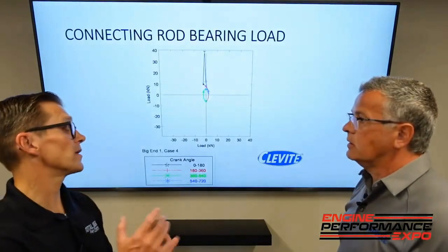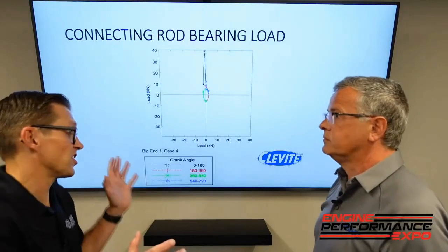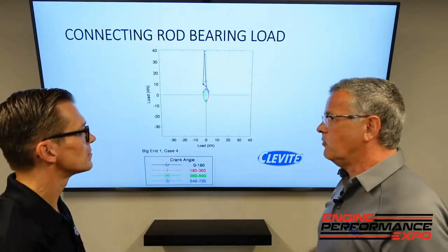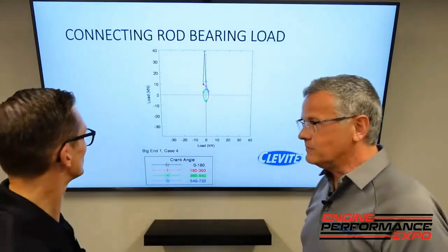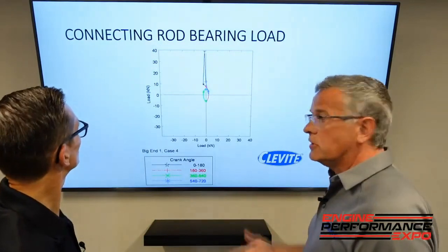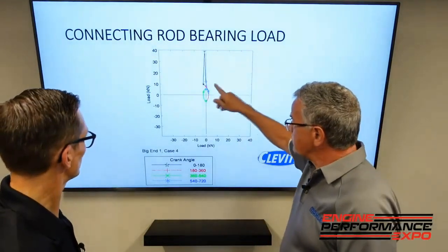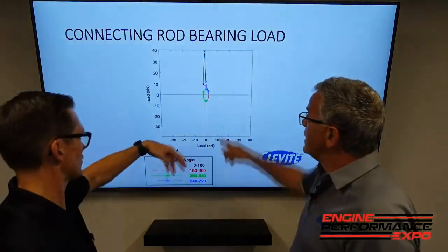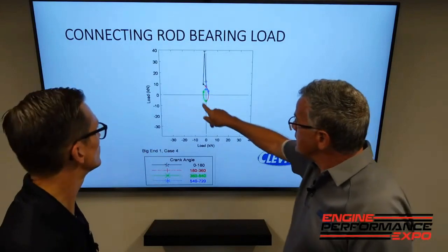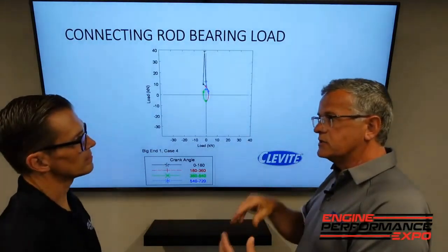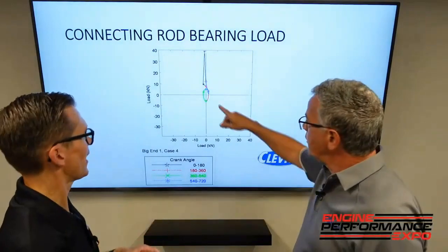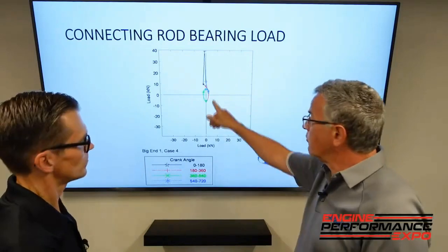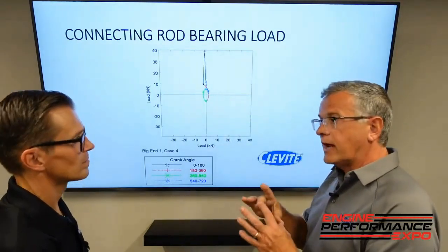It's a big issue also in rolling element bearings. Fretting is an issue, rolling element or plain bearing. Moving components need to move in harmony. Now, connecting rod bearing loads. Over 720 degrees of rotation, notice that the loads change dramatically based on where they are in the cycle. As you would expect, the load creates more of an oval, so your housing bore in a connecting rod will follow that shape. Your housing bore can actually open and close.